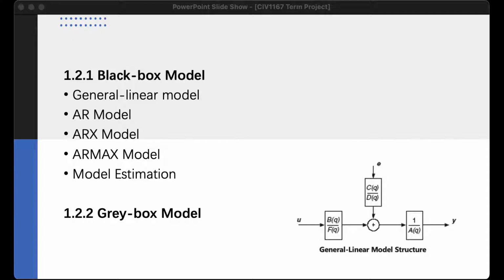First, obtain useful information about the model order by observing the number of resonance peaks in a medium-size ARX model. Choose the delay that provides the best model fit based on prediction errors or other fit criteria.